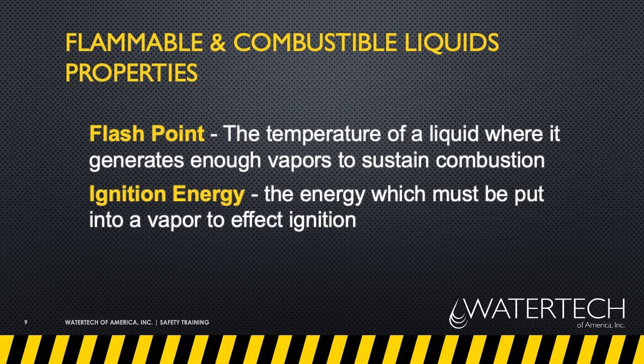Flash point is an important term. The flash point is the temperature of a liquid where it generates sufficient vapor to sustain combustion. The flash point is an important safety measure, as substances with lower flash points are more volatile and can ignite more easily. The term ignition energy refers to the amount of energy required to initiate combustion or ignite a substance. This energy can come from various sources, such as sparks, flames, or hot surfaces. Different substances require different levels of ignition energy to ignite.